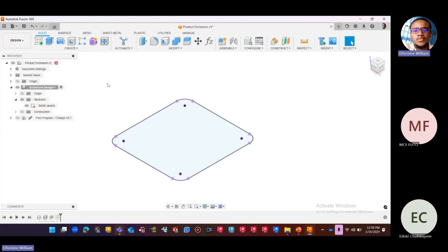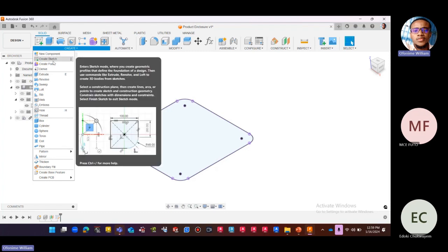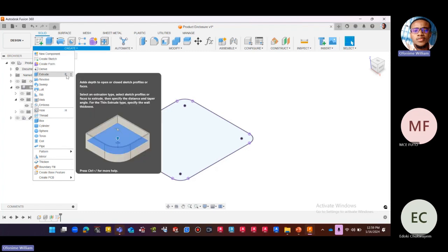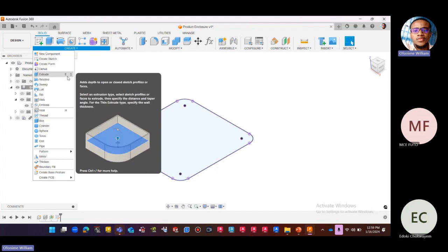So even those things you're thinking about to do, first of all, you must create something, then you have to modify the thing to look like what you want. Then when you're done, probably you have to assemble them and then start pushing. That's why you're seeing it arranged this way. So even the sketch, if you see, it's still part of Create because you created the sketch first before extruding. So please take note of the shortcut E. So next time, we might just click E on the keyboard to activate that command.